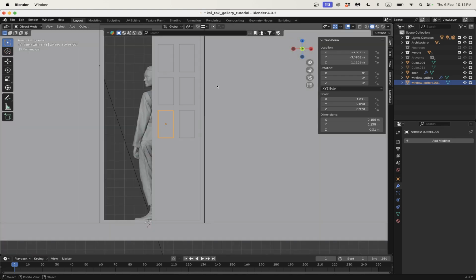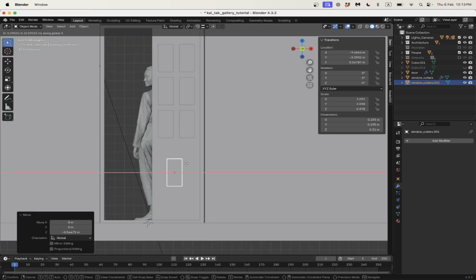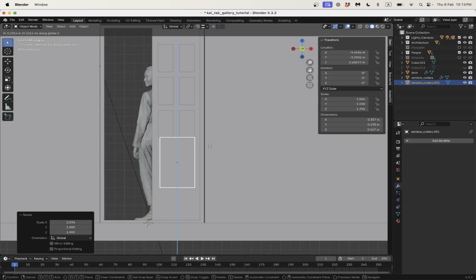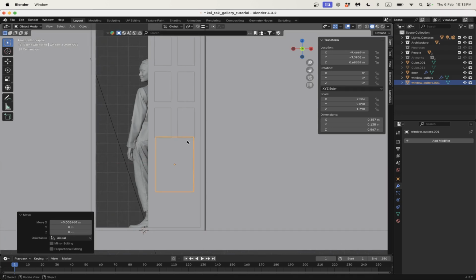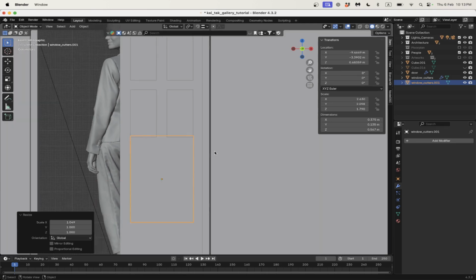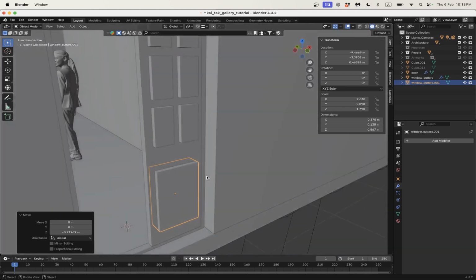And if I look back down on my Y here, I can go GZ, GX, scale it up a bit, scale it on the X axis and the Y axis, and I'm going to have it so that it's the same width. So I will go SX until it's the same width, and then GZ, and I'll pop it down here.